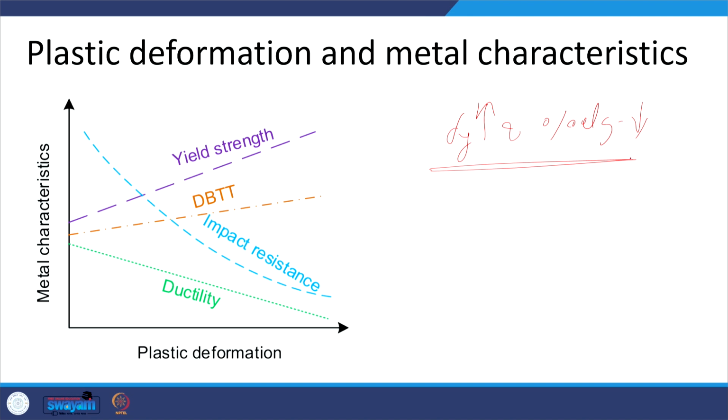So, from the ease of deformation point of view, this change is undesirable, because for easy plastic deformation, if the material has a lower yield strength and higher ductility in terms of percentage elongation, then this will result in easy plastic deformation of the metal to get the desired size and shape during manufacturing by deformation based material processing techniques.